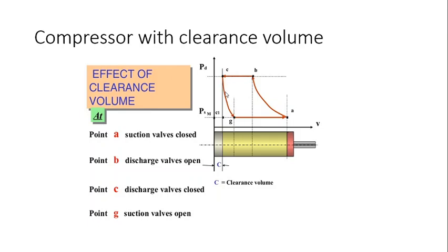During this expansion process, the compressor will not suck air from the atmosphere. So this expansion process is an effect of clearance volume.